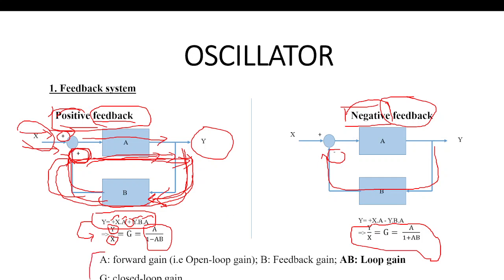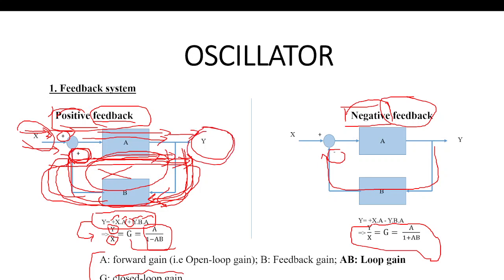Now let's go to some definitions. We call this formula the closed loop gain. Why is it closed? When you look at this block diagram, everything is closed as a loop. So this loop is totally closed. We call it closed loop gain. When we don't consider the feedback branch, only the input signal goes through the system A to the output signal y, we have an open direction.